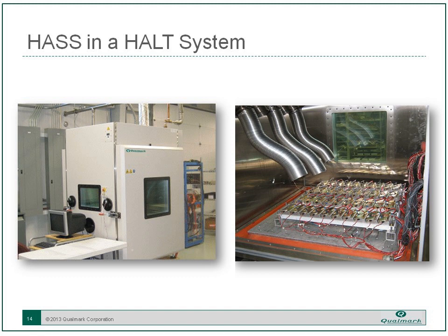Here's an example of HASS implemented in what you think of as a typical HALT chamber. This is a Qualmark Typhoon 3.0, I believe. It's a 3-foot by 3-foot table. And this is in a facility that is doing high mix, low volume specialty power supplies for the military. So we have a test rack here by the chamber, and here is one configuration of power supply being tested with ducting being used to direct air down onto the product.